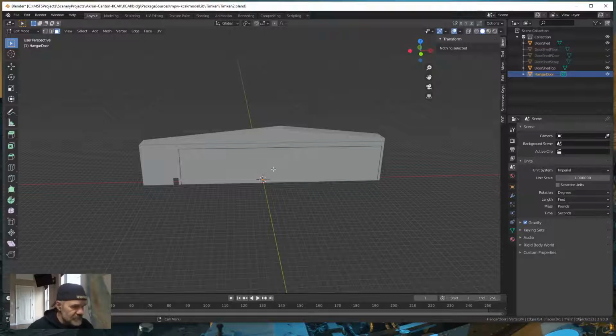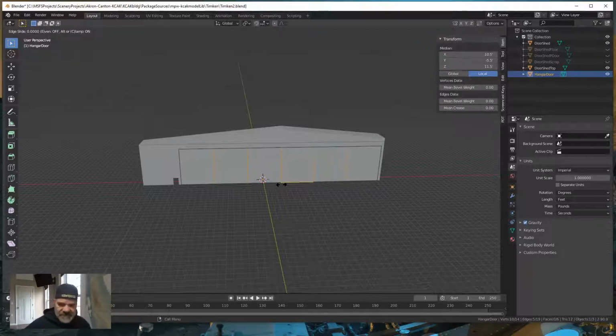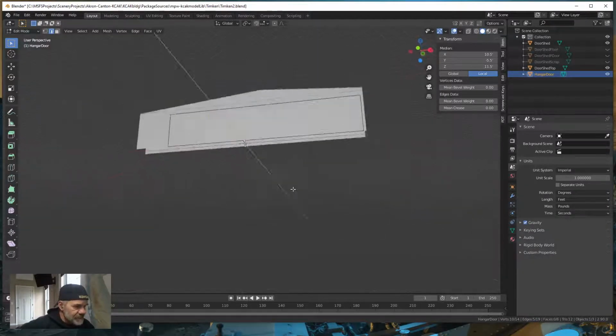edit mode. So now we're just going to make a loop cut. So that's Control R. And if you use your scroll wheel, it adds loops. So there's 3 polygons, 4, 5, 6. All I did was move the scroll wheel to add loop cuts. So now I have 6 doors. Now I can hit enter and hit escape so I don't move them. Okay, so we have those.